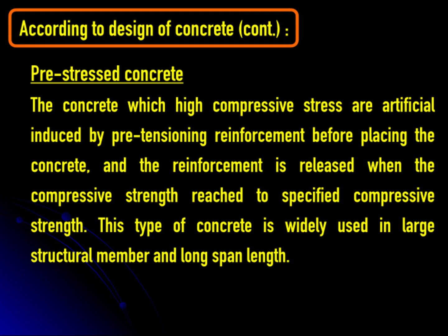Pre-stressed concrete. Pre-stressed concrete is used in various buildings and bridges. It allows for longer spans, reduced thickness, and material savings. High tensile steel is tensioned before or during casting to apply initial compression. This compression counteracts future tensile forces, improving the overall performance.